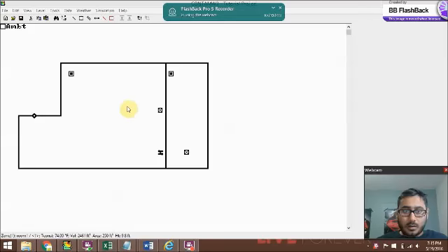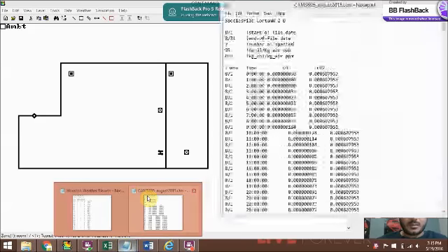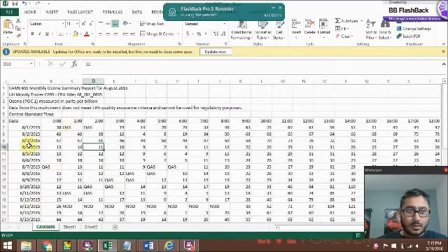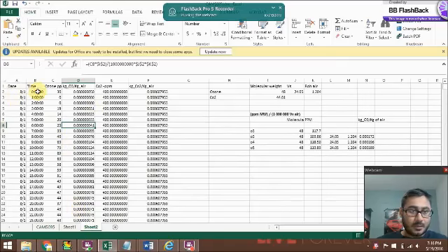So once your occupants, your species, and your HVAC is set up, the next step would be to set up ambient weather file and ambient contaminant files. So the next few steps would be to guide through an Excel file. So here we have, once you have all your measured data based on your time and your PPB, this Excel sheet would help you to create based on per date and time and the ozone PPB. Here I've added two contaminants. One is ozone, one is CO2.